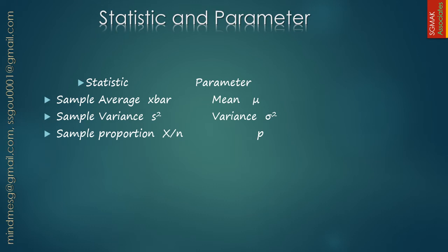So in this case, your sample proportion from the randomly drawn sample from that batch is 1 over 100. And the corresponding parameter is represented by small p, known as fraction defective. So we may state that our process is giving on average 1% fraction defective, which is making about, on average, one defective part every 100 parts.